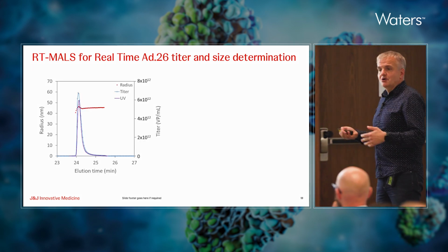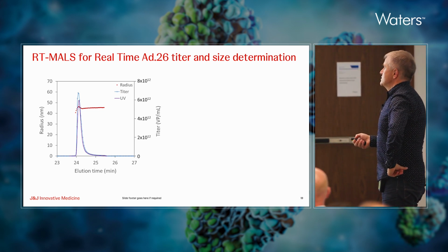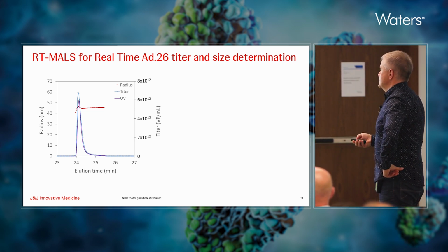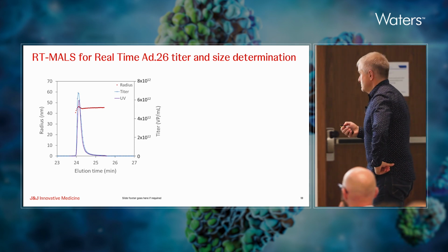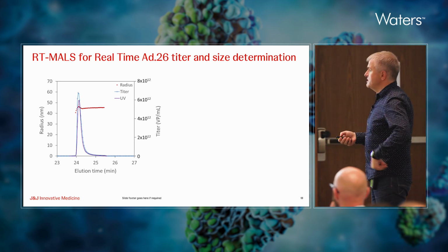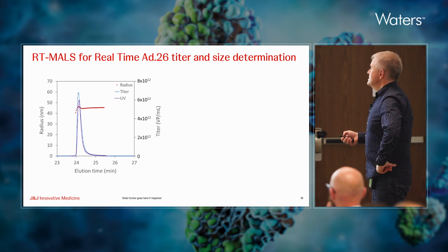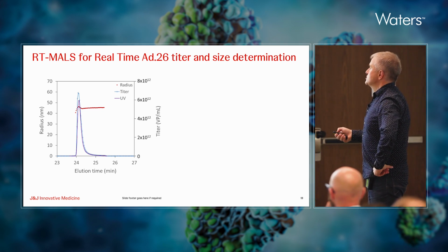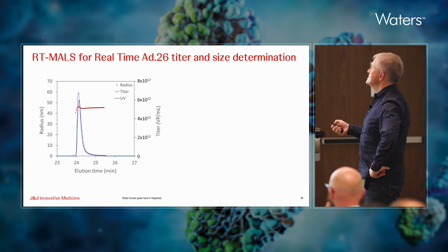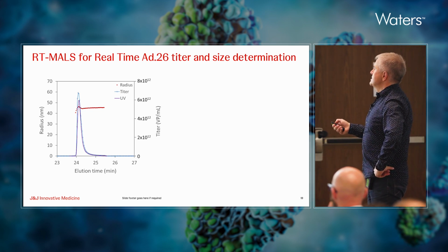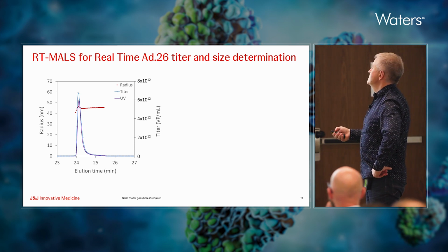Of course, when the material is on the column, you also want to get it back, because that's fair. So this is just a representation of the elution process. There is no gimmick in the separation per se, it's more like the detection. So here you see again the elution profile by UV, and you can also measure the titer using the light scattering data.